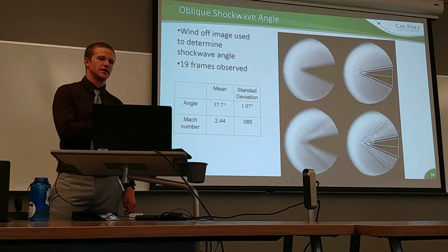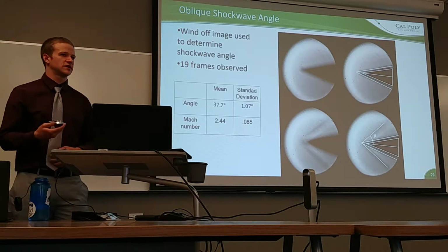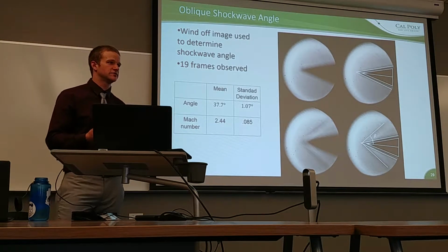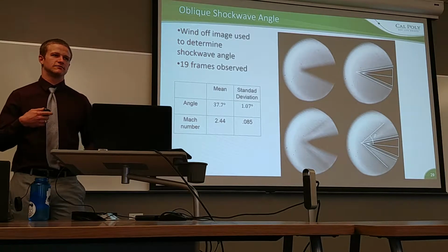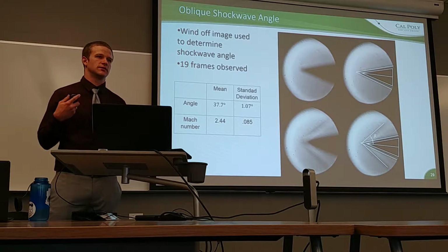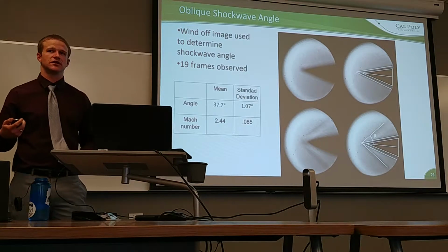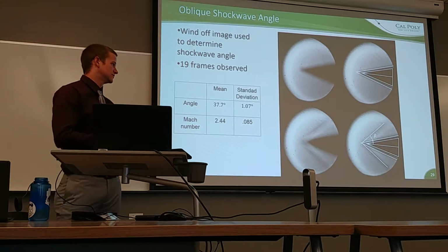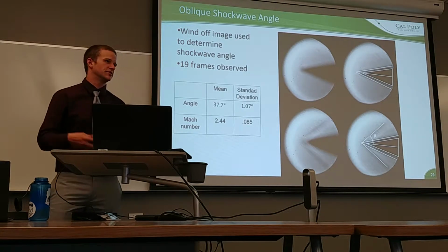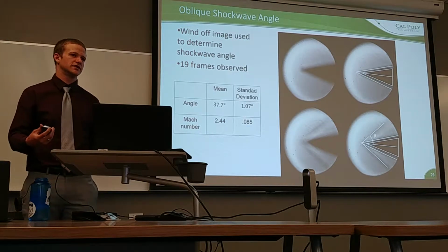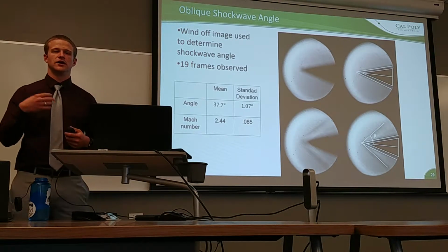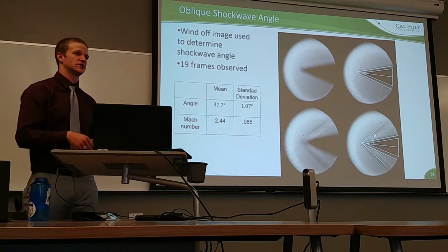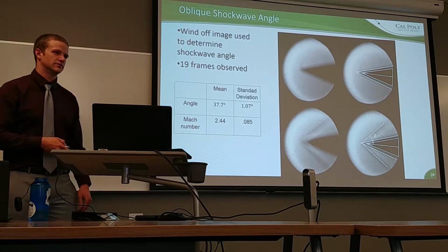Also, viscous effects weren't taken into account in the design of the nozzle, and the actual tolerances on the machined nozzle are wide enough to cause a similar deviation in Mach number. But I think the primary goal of validating supersonic flow is achieved with this analysis.